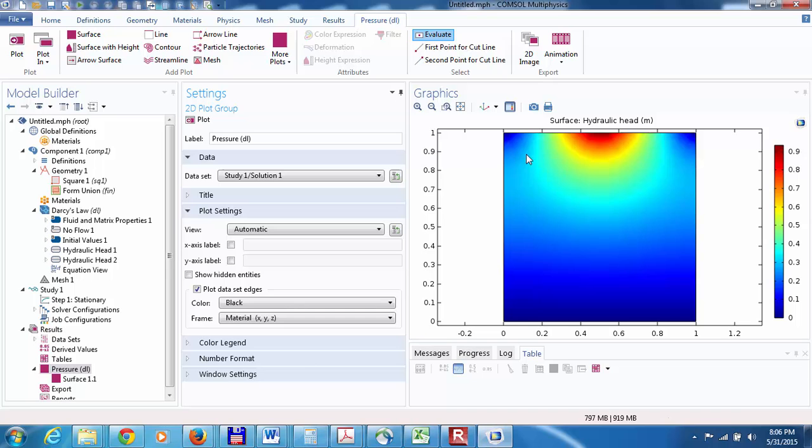Basically, you can see that we're going to have this flow going like this, and of course there'll be flow going through the bottom boundary. I do this because by having this non-uniform hydraulic head on the top surface, we'll have more irregularity in the flux, and that's more difficult for just the pure Darcy fluxes to compute the flux across the boundaries. This procedure for calculating accurate fluxes will be superior to using the Darcy fluxes to calculate the fluxes across the boundaries.